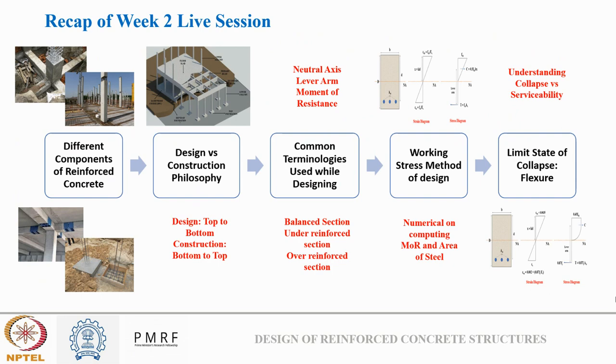neutral axis, where the net stress is zero; lever arm, that is the distance between net compressive and tension force; moment of resistance, which is offered by a component due to the couple of compression and tension to resist the external load. We also discussed balanced, under-reinforced and over-reinforced sections of design, where the ideal one is balanced but not practical. So for safety, we provide an under-reinforced section.